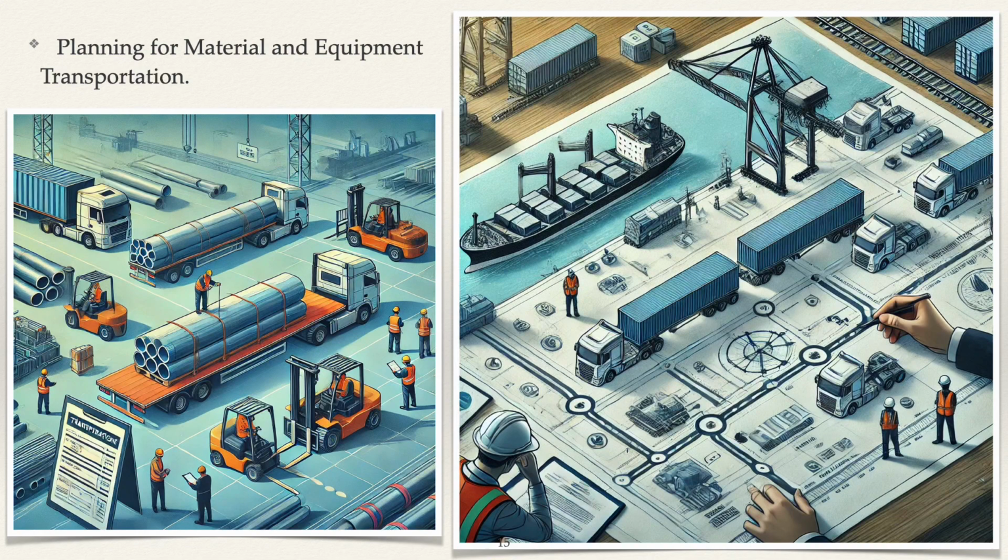Transportation route planning: plan transportation routes based on site access points, sea route and road conditions, and potential obstacles. For remote or challenging sites, consider alternative routes that accommodate oversized loads and minimize environmental impact. Oversized and heavy loads: identify equipment and materials that require special handling, such as tower sections, large transformers, or cranes. For these loads, the logistics agency may need special permits,